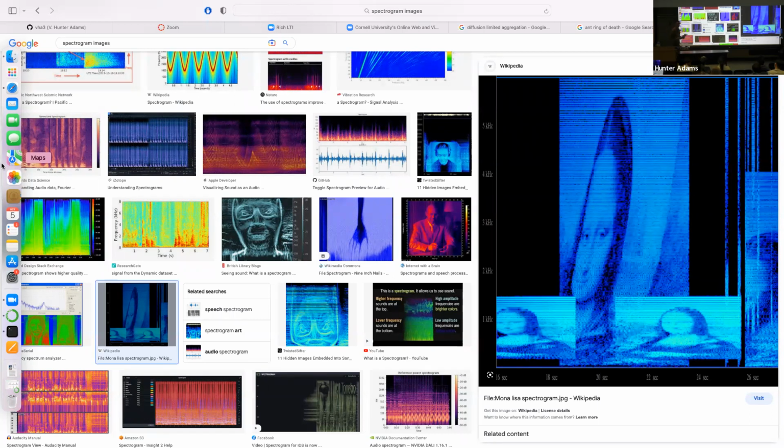You could do all sorts of synthesis projects. You could synthesize various animal calls. Birds are a fantastic one, particularly songbirds. Songbirds whistle. They really only produce one tone at a time. So you can generate that tone with one direct digital synthesis synthesizer. And then if you modulate that frequency that that synthesizer is generating correctly, what's correctly mean?